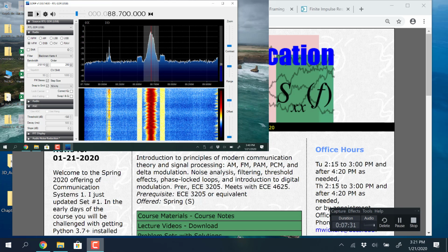If you tune on the FM broadcast band, you'll notice everything goes in odd multiples of 100 kilohertz: 101.1, 101.3, 101.5, 101.7. But even with that being said, most of the stations that are put up in a locale or market, I guess they call it a market, the Colorado Springs market is distinct from Denver's market because we have Monument Hill, which kind of acts as a barrier for the RF at that frequency from bending and coming down. It's too high a frequency for it to really skip very well like lower frequencies would. So those are two markets.